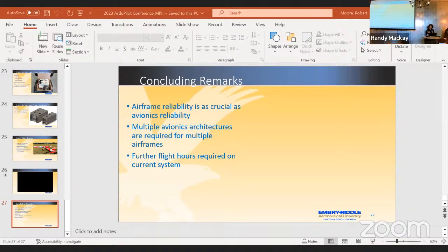The only time you need to synchronize is if you're doing more advanced things, like keeping the two navigation controllers on the same leg of a waypoint and that sort of thing. Yep, and to bounce off what you said with the whole I gain thing: in the early days of the RV8, I made the mistake of putting both in auto for ArduPlane. The I gain ran away and then all hell broke loose when it deflected controls to max.